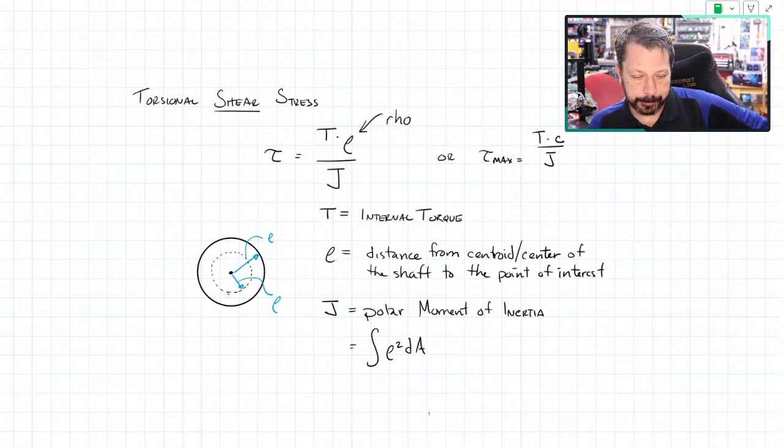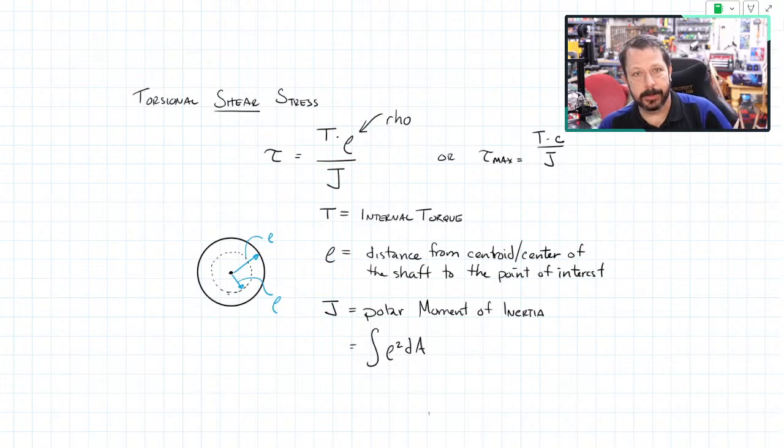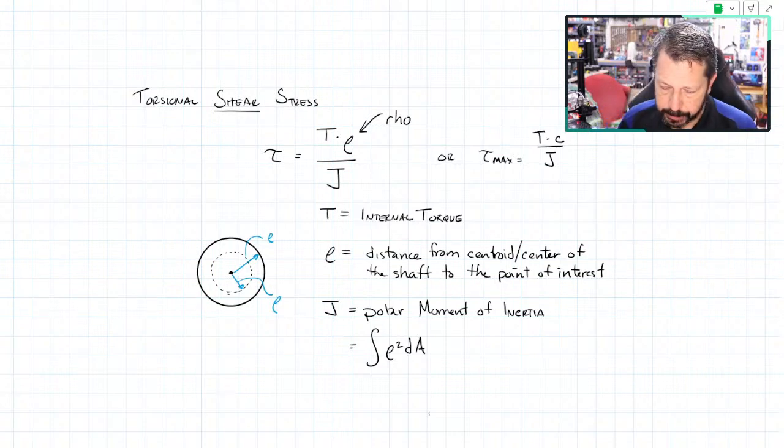If you had to do another shape, the problem with hexagon shape cross sections and things like that is that you'll get stress concentrations at those edges where they meet, whereas a round circle, you don't get those concentrations. So there are sometimes reasons to have a faceted shaft. Maybe it's got to interface with something, and that's the way you're going to interface it. Like it's a drive shaft that plugs into a socket somehow, and if it was just a circle, then it wouldn't grab it. It needs to be some kind of shape. Those you have to treat a little bit differently.